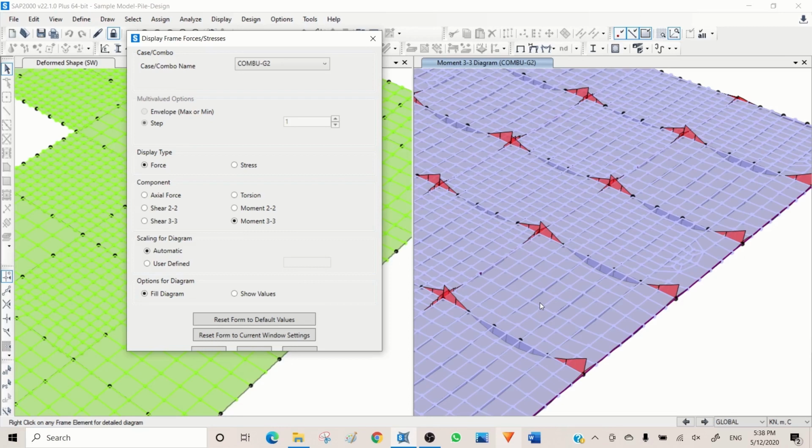But again, what is the reality? You really need to see what is the stiffness of a slab here, how much load can be transferred by a slab to the support, and what is the actual stiffness of the beam here. Is the actual stiffness of the beam here correct? The answer is no, because this beam is acting like a composite beam. This beam has a flange of the slab on top, so we need to modify the stiffness of the beam. We will talk about it in the last part of our module about design of composite beams and design of steel beams. So be patient and I will get back to you on this.